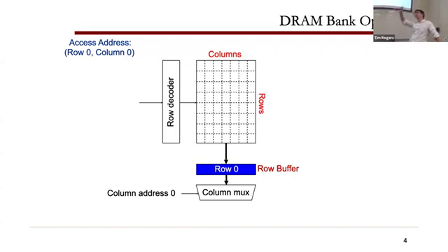I just have some control lines on the mux that essentially take the column address to figure out which part I'm going to put down on the wires that I actually have. The data wires are not wide enough, they're not a whole row. They're much smaller. You're talking about rows on the order of 1,000 bits, and then data wires on the order of 8 bits or something for each individual bank. Okay. And again, these can vary, but that's sort of the ratios. Then the data will come out.